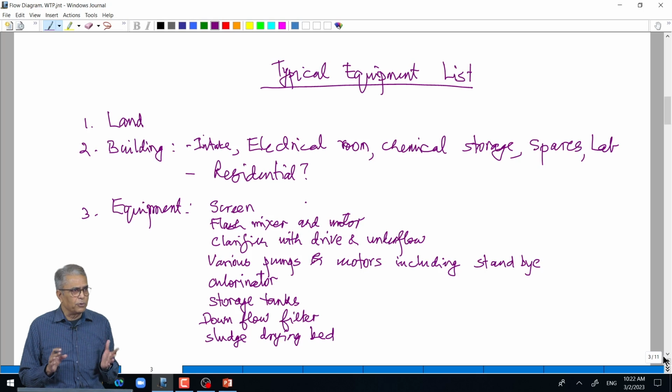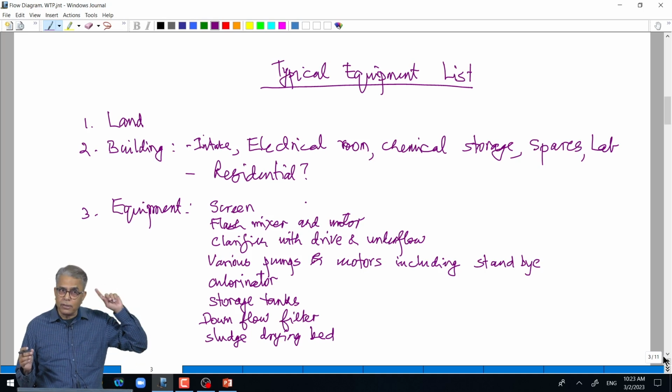If you do the detailed calculations, power requirements will be about 50 to 75 kilowatt. Now, 50 to 75 kilowatt only for the pump, then there will be a room, there will be lighting, the guy is going to sit there, an operator, whatever it is, there will be some space required for him. So, all this building, lighting, path where he has to decently go in and out, access, all that, you calculate, power has to come from somewhere. So, you may find that you have to think of that in mind.